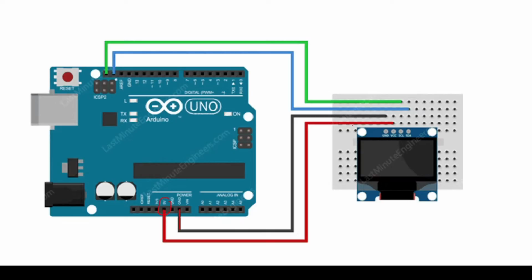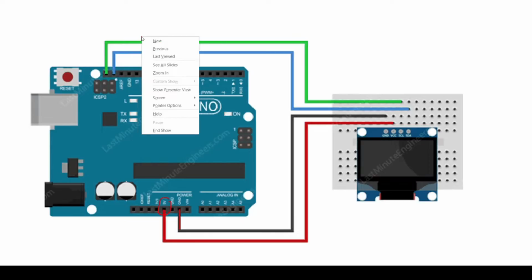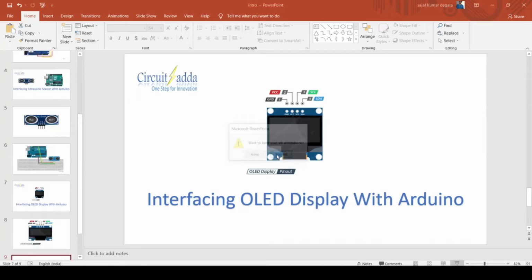If you go through our first video, where we explained the Arduino board, we explained that we have many pins here. Some of the pins act as IIC communication pins, and some can be used for SPI communication, right? You can easily find that by Googling the name with "pinout", and then you can see which pins are used for SPI or IIC. Let me show you so that you don't have any confusion.